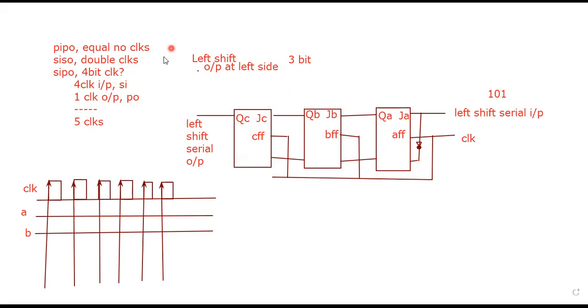So now, let me draw A. According to the clocks, at the first clock, we would have 1. Here it is 1, and it would be 1 for the next clock as well. Then there is 0, and at the third clock we just copy the message 1 0 1. Okay, 1, 2 and 3. At the third clock, these 3 bits would enter into the A flip-flop.